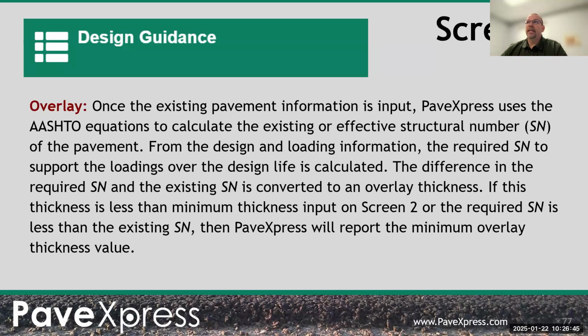Say where you had a 6-inch base and 4 inches of asphalt, and we crush and shape the 4 inches with a couple inches of the aggregate base, we could put that into our new design with 4 inches of base, and then an asphalt treated base, and then build on top of that. So I wouldn't use the overlay part of this to do that. Yeah, you can still use this software, just not this part of the software. I'd characterize that more as kind of a new construction, reconstruction, I guess, a new design. Great.